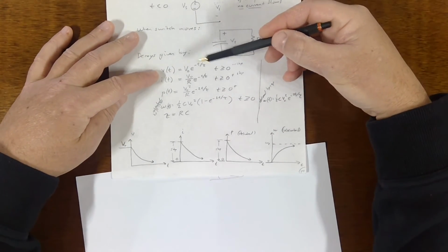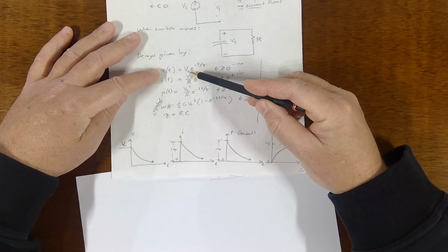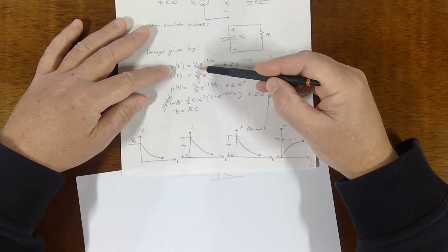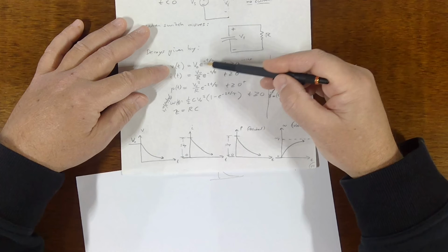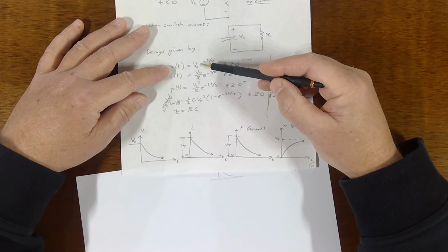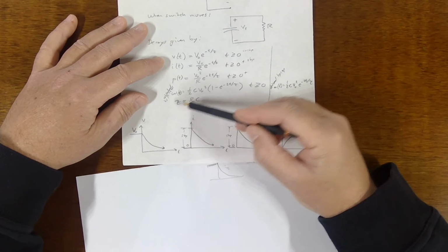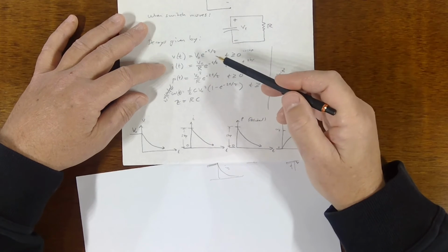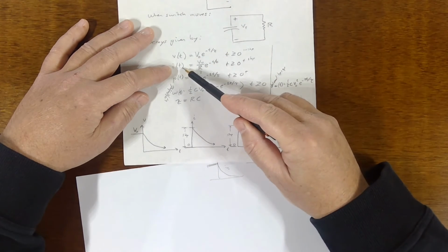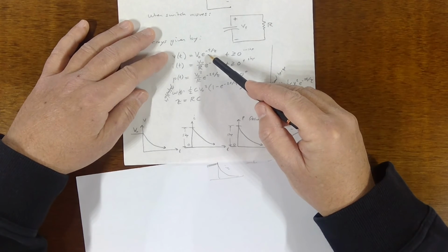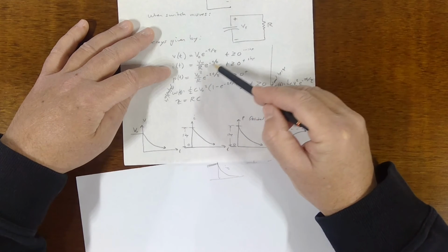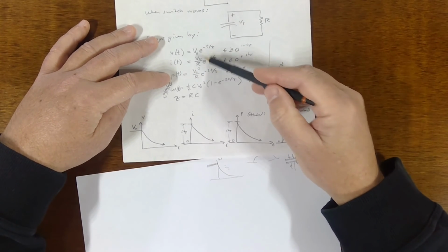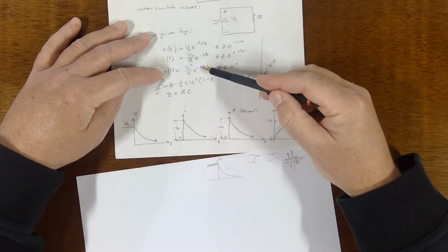That's these two equations. So voltage is the initial voltage, V0. In this case, V0 is Vs. Then this is the exponential decay envelope, e to the minus t by tau, where tau is RC for an RC circuit. And by Ohm's law, I is V over R, so you take this V equation and put R on the bottom, and you get the I response, the current response. Multiply these two together, you get V squared over R e to the minus 2t by tau.